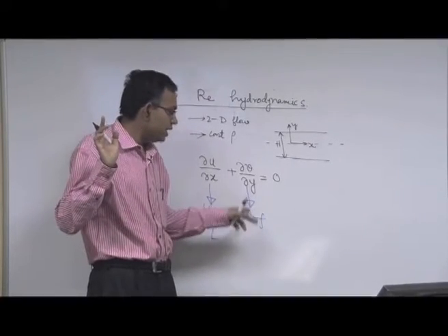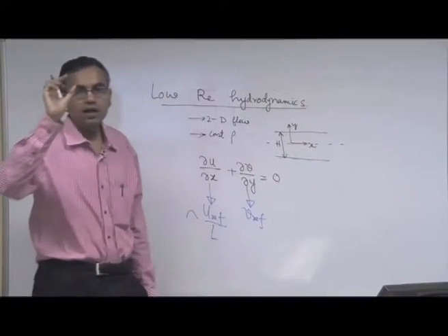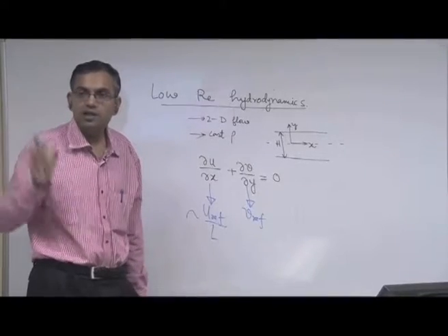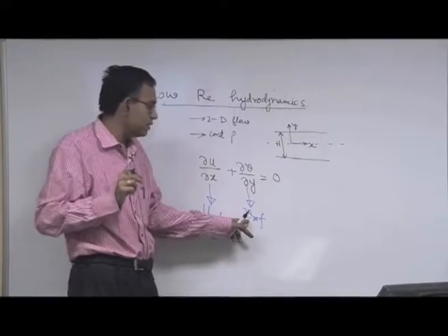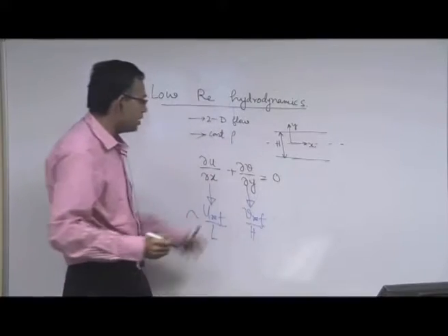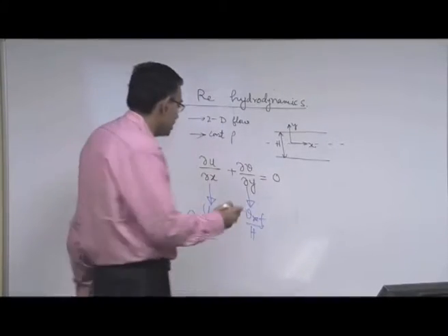Now here we are bothered about low Reynolds number flow, because in microchannel the characteristic length scale is small, that makes the Reynolds number based on the characteristic length scale small, but V is not identically 0. This V by H, it does not matter whether you write H by 2 or H scale wise, order of magnitude wise it does not matter.